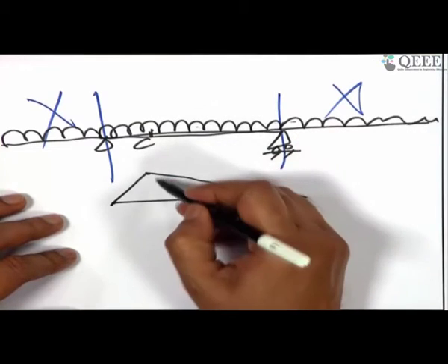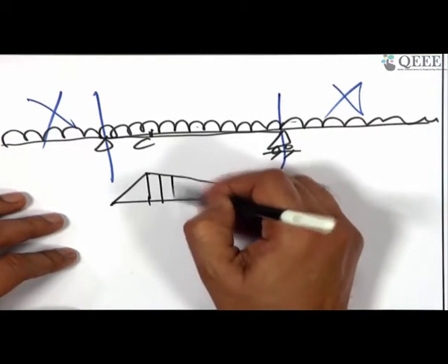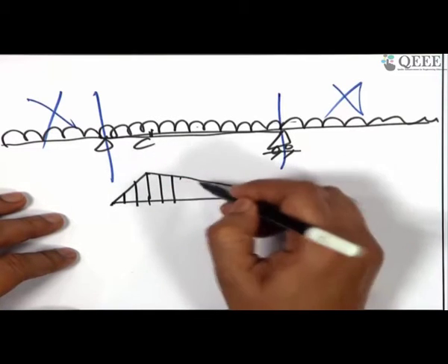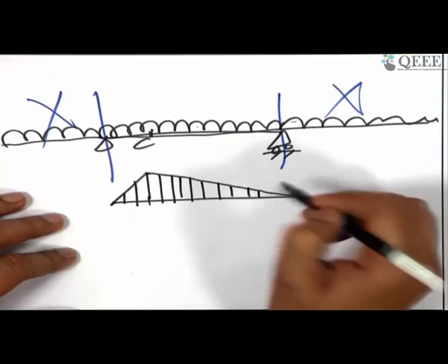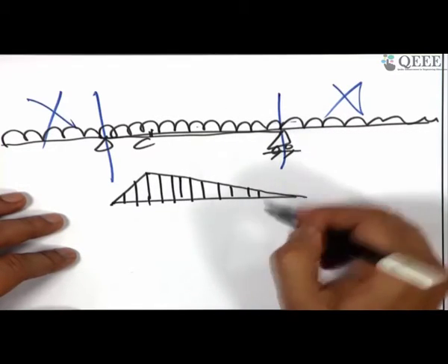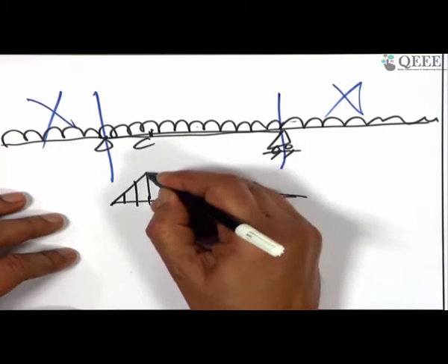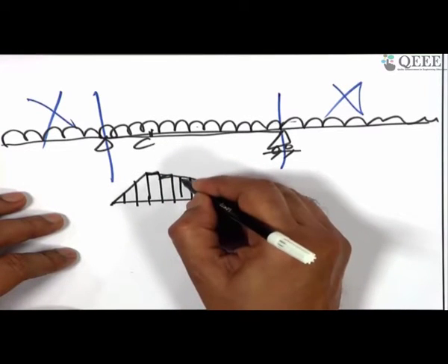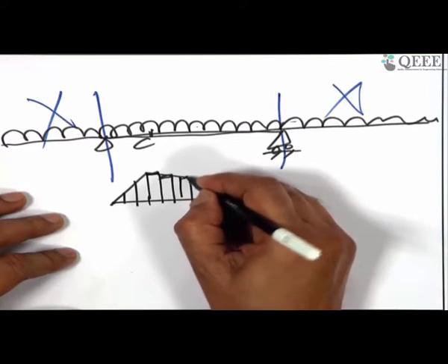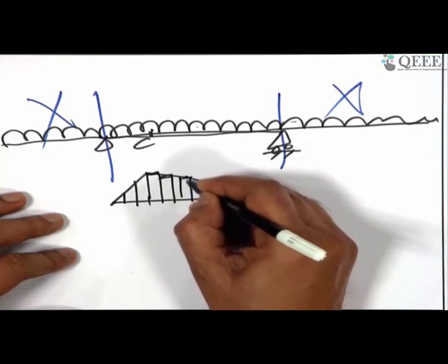If your question is how to find out the ordinates for this, in fact, I have told you that it is the area of the influence line diagram multiplied by the UDL. If you are still not satisfied and are searching for the ordinate for a UDL in an influence line diagram, divide it into several parts, and also divide it into rectangles by drawing lines from the midpoint, so that this small triangle and this small triangle compensate each other.